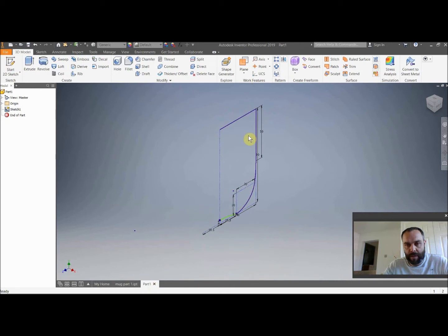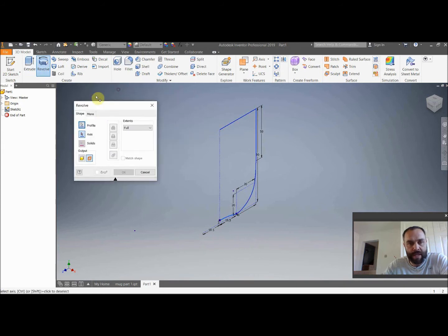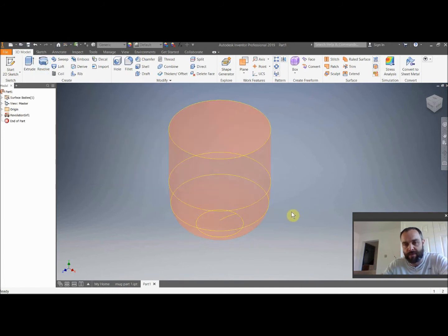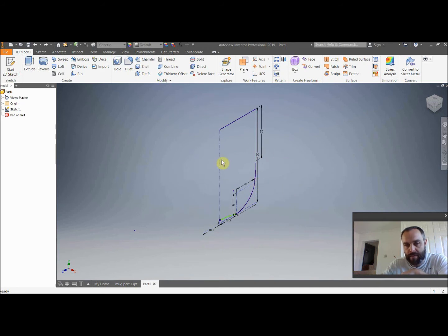Okay, so going back to my sketch, we just created this sketch. Now one thing I want to be mindful about at this point, I've deliberately placed an error into this sketch, and that was leaving this revolve axis as a construction line here. The reason I've put this in is a frequent thing that I see students doing: they work from a profile like this and move on to an extrusion or a revolve or any of these 2D to 3D tools, and they click onto the axis and choose the axis like this, and then they wonder why it comes up red like this, and if they click OK it comes out with no actual solid object. The reason is that this is not a completed profile, and it's because of this construction line here.